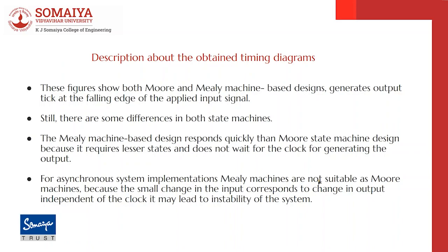Still, there are some differences between both state machines. The Mealy based design responds more quickly than the Moore state machine because it requires fewer states and does not wait for the clock for generating the output. For asynchronous system implementation, Mealy machines are not as suitable as Moore machines because a small change in the input corresponds to a change in output independent of the clock, and it may lead to instability of the system.